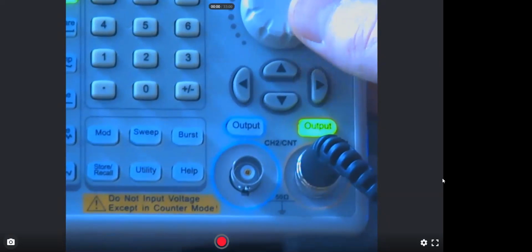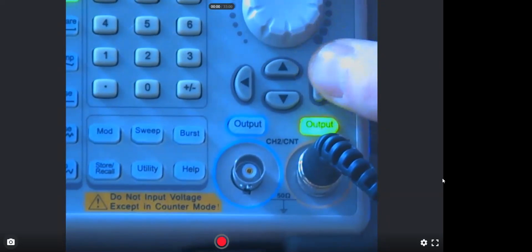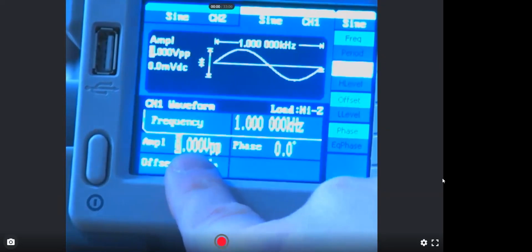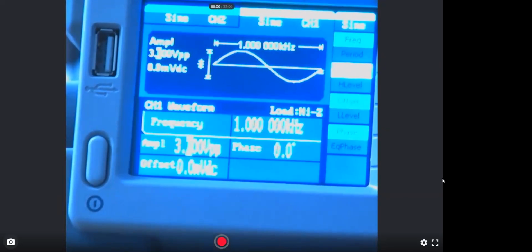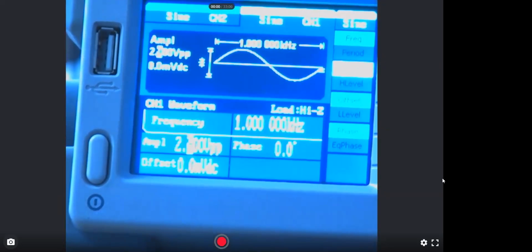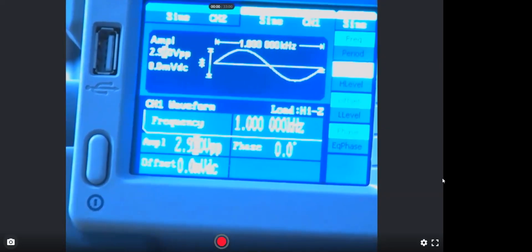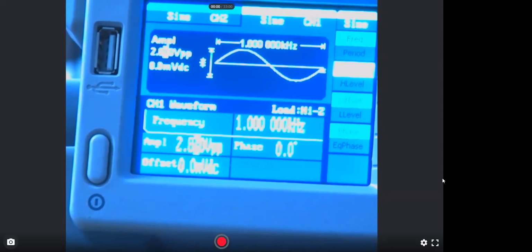To do that, underneath the knob where you adjust the amplitude, I'm hitting these arrows. When I hit those arrows, it'll change from this to this decimal, right? So I go over here and take this to 2.9. That gets me a little closer to 1.00 volts AC on my meter. Then I'm going to go to the second decimal and go down to 2.8.